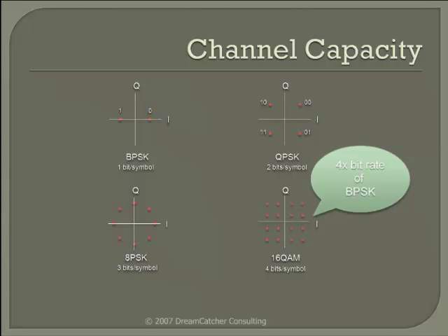But there is a trade-off in packing in greater channel capacity into the same bandwidth. The areas shaded in gray show the allowable deviation in the symbol location for BPSK and 16 QAM. BPSK has much greater allowable deviation than 16 QAM before a symbol crosses over to another symbol's location, which would result in symbol error and hence bit error. So the trade-off for higher channel capacity is a lower tolerance to nonlinearity, distortions, and noise.